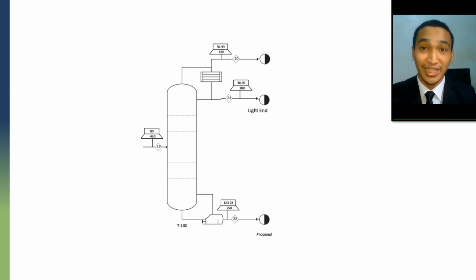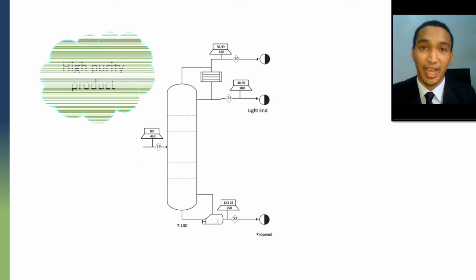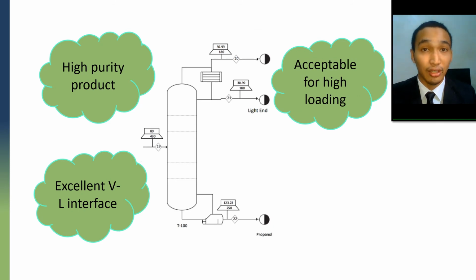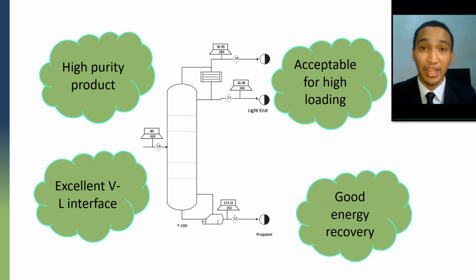Why do we propose the distillation column as our separation unit? Because of these four factors: high purity product, excellent vapor-liquid interface, acceptable for high loading, and also good heat and energy recovery.